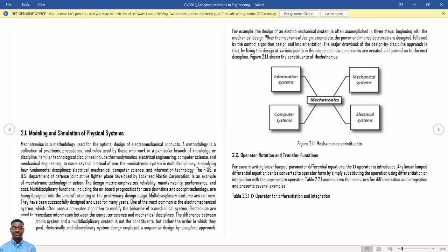So the sensor measures the output speed at the output shaft and reports to the algorithm, which is basically the computer science aspect of the system. The algorithm checks if the measured speed and the set point are equal. If it's not equal, then a computation algorithm such as your PID controller can be used to compensate for the voltage that would make up for that difference in speed between your input and your output.